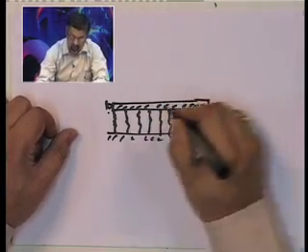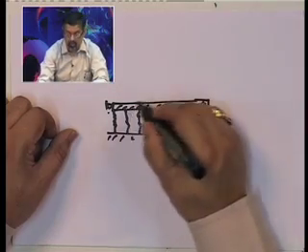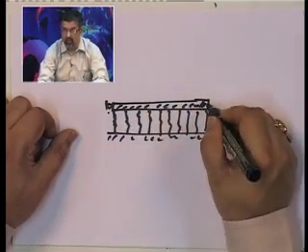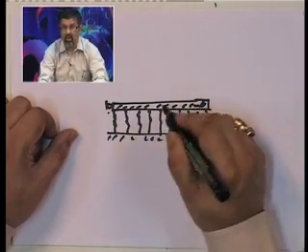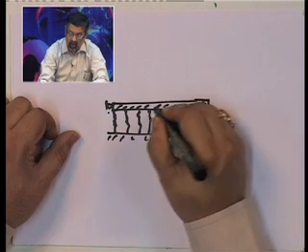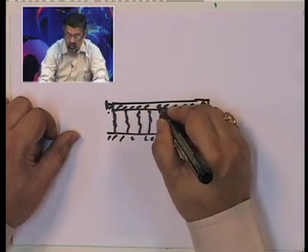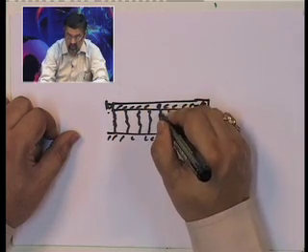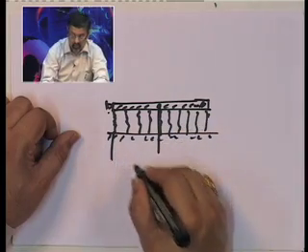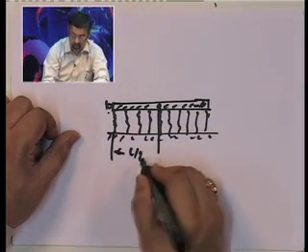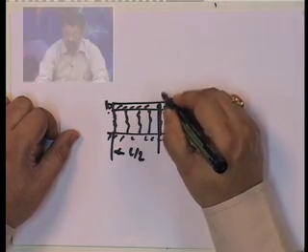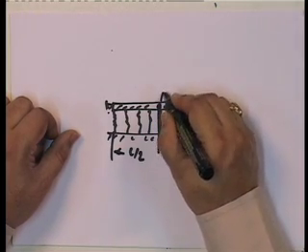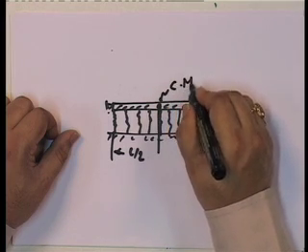Okay. So, if we look at it, I can define this structure as a 2 degree of freedom structure by saying that, look, this is a rigid beam with uniformly distributed mass. The mass m bar is a constant. So, the center of mass of this bar will be where? It will be the center, which is L by 2. So, let me take the center of mass of the bar and let me say that this is the center of mass.